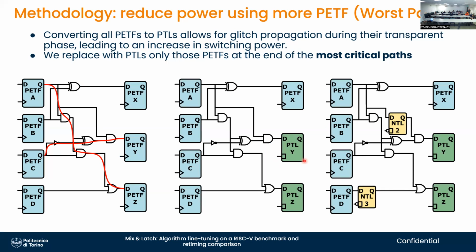Sorry, I have a question. In the example on the bottom, the middle bottom. Imagine I have an AND with an input wire. Now that AND, because it's close to the end, can create a fault violation because it can go very fast. For some values it can be a long path, for some values it can be a short path. But if I convert it to a latch, then how do I handle the case that some values could have been a fault violation?